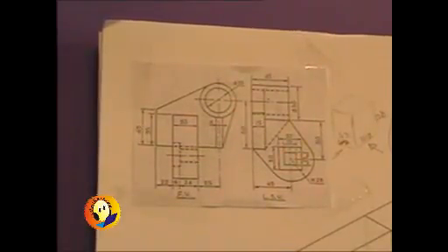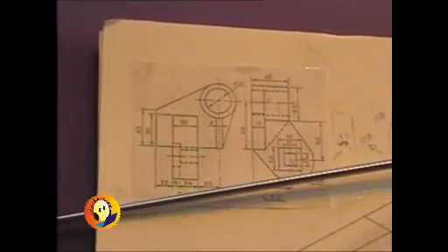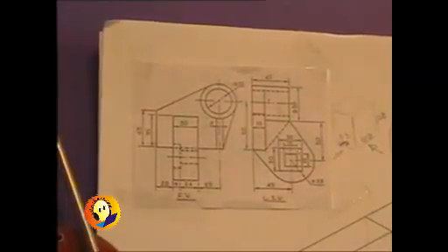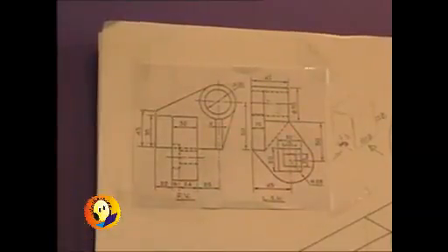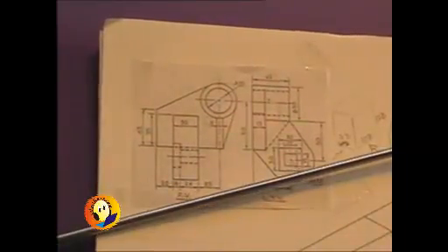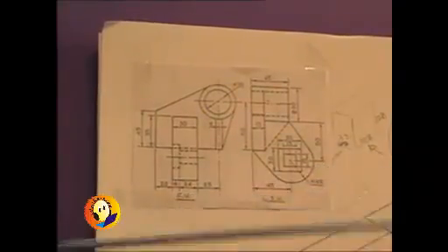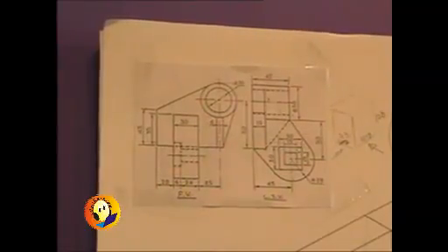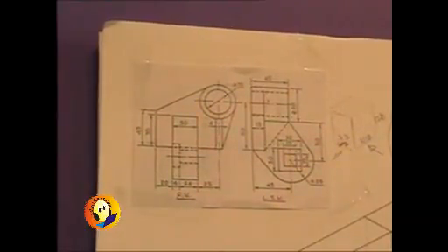All the lines should be drawn. First of all, the box is to be completed. So if you are drawing it with me, I have already started with horizontal line, vertical line, drawn two lines which are making 30 degrees. On the right hand side 30 degrees line I had measured a distance of 100 millimeters, whereas on the left hand side 30 degree line I have measured a distance of 73. Along the vertical line, that is the height, I have measured a distance of 128, and now I have completed the box, marking the 3 points and then drawing lines parallel to the 30 degrees lines as well as the vertical lines.